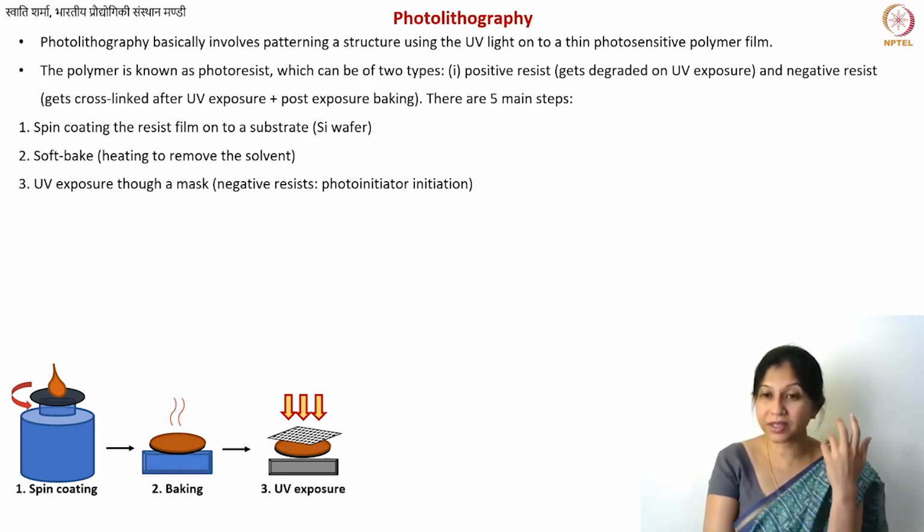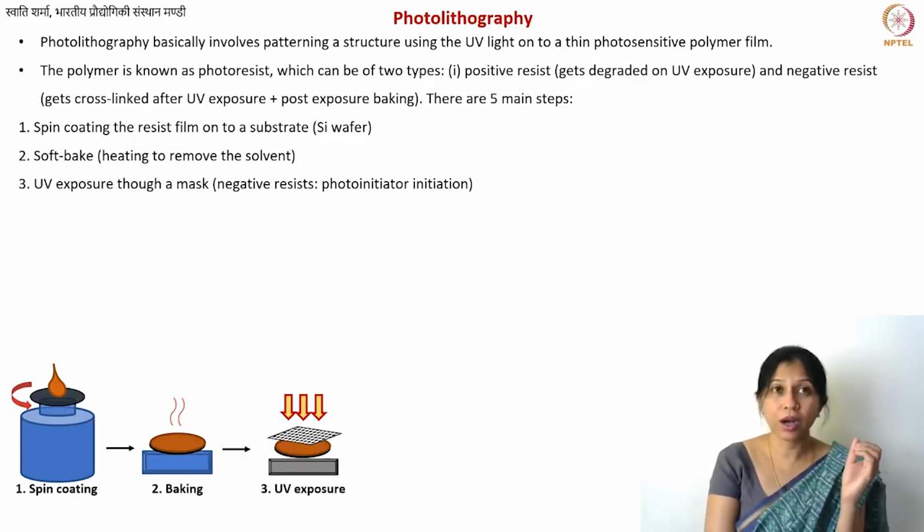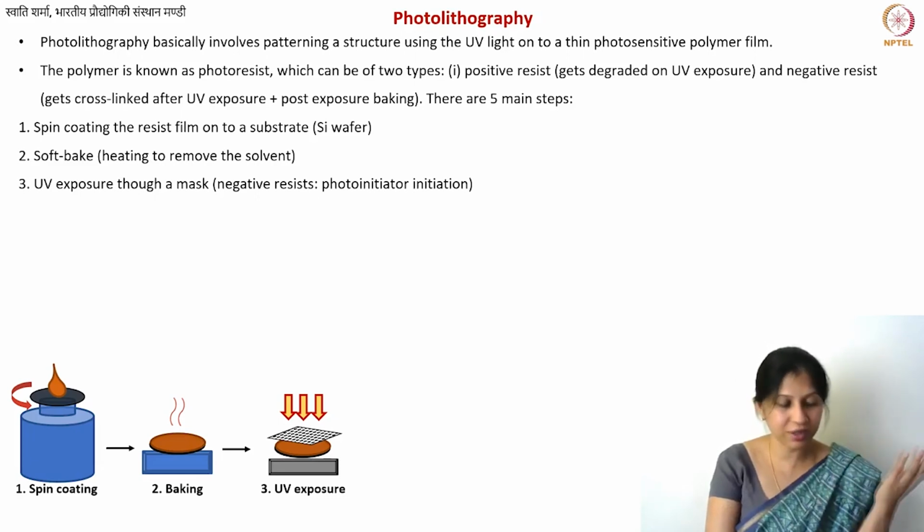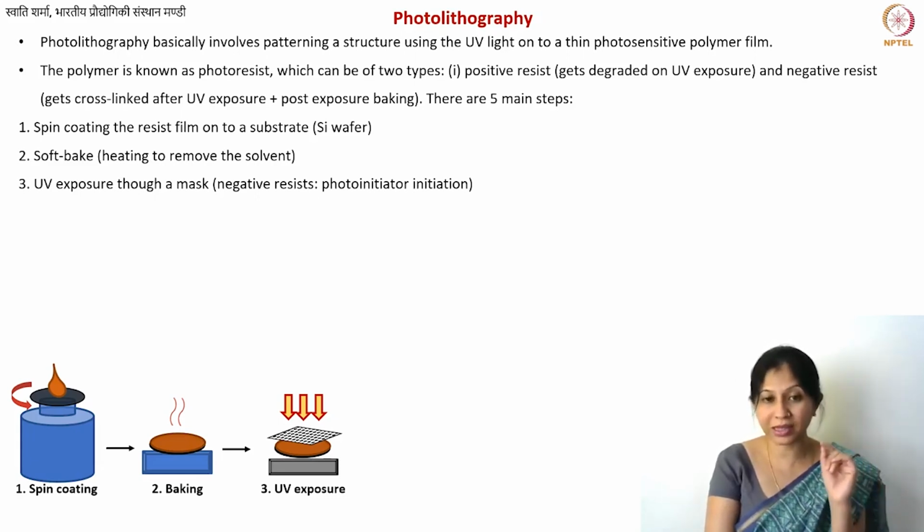in that case you need to use very sophisticated techniques, and you need to do this printing of masks using certain metals. You use things like electron beam lithography just to make the mask, and you use metals like chrome for making the mask as the inks. So now the mask itself can be really expensive, and it's not just about expense, the fact that you want to utilize it for several batches. You want to have the exact same structures for several batches, so you don't want to damage your mask, and that is why the baking step was also important.